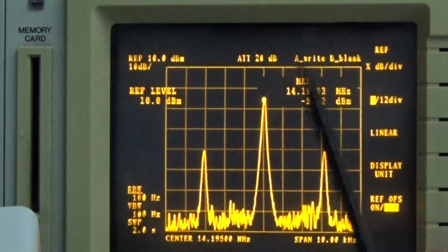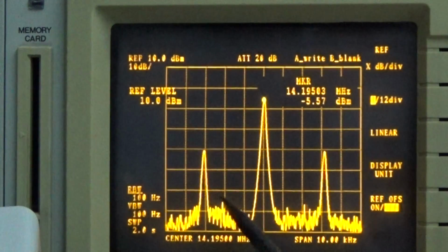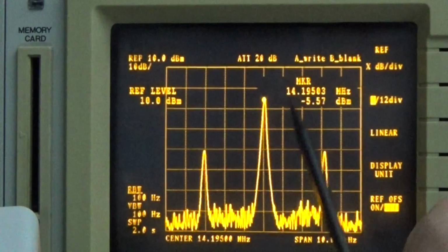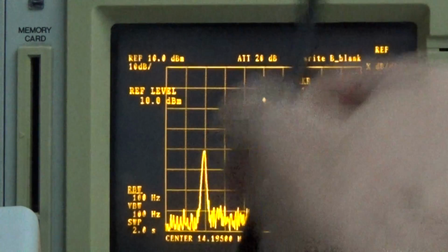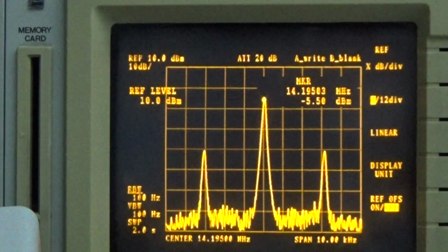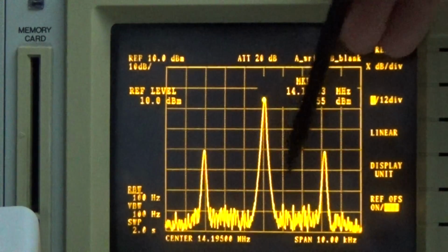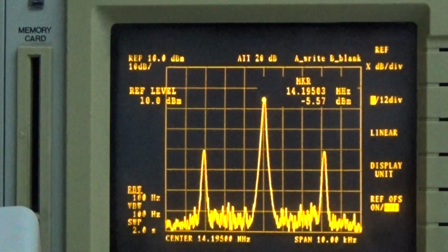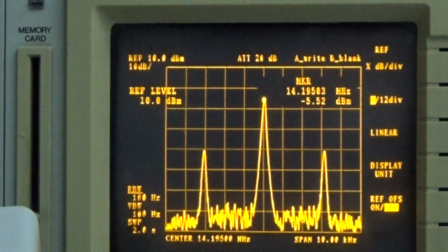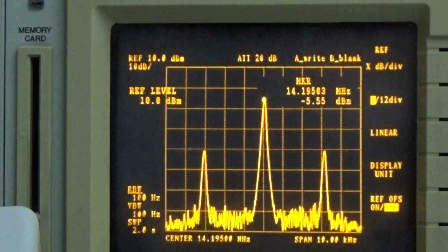And if we were able to suppress the second sideband as well, which we don't need, and it doesn't matter if it is the upper sideband or the lower sideband, then we would only need a bandwidth of maximum 3 kilohertz, and that means we would get double the number of stations theoretically on the same band.